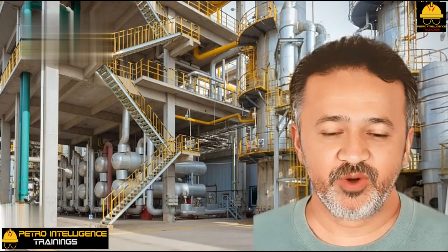Side stream stripper hydraulics. In a project, a young engineer was to improve the quality of jet fuel from a side stream stripper. Initially, he had thought the problem was due to poor stripping efficiency, but it was really a simple problem in hydraulics, the part of technology that deals with the pressure drop of gases and liquids flowing through pipes and other process equipment. Liquid heads, gravity, and friction are all parts of hydraulics.